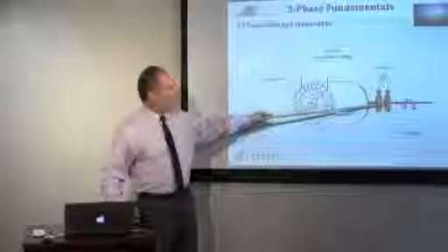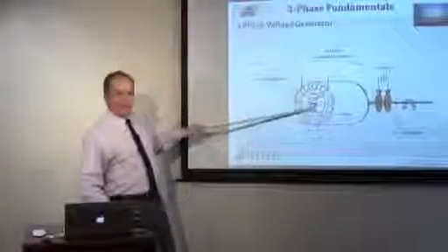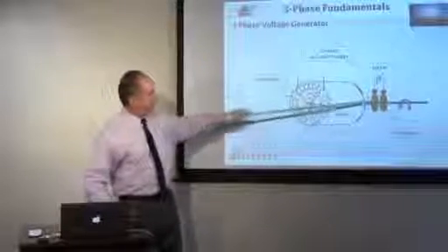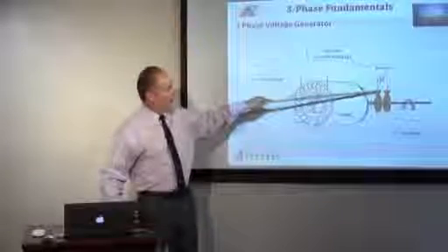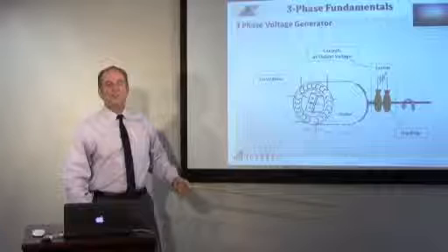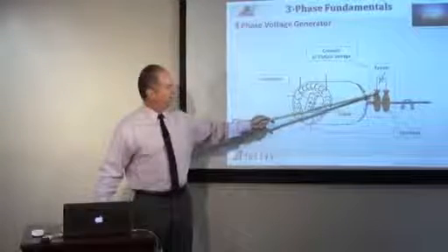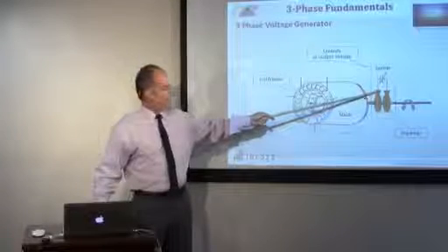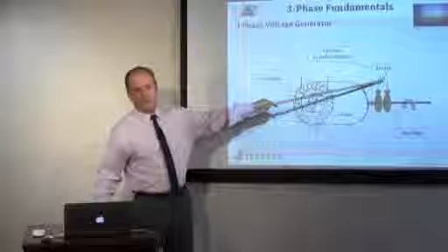It has slip rings connected to the shaft so that the 2 wires from the coil can be connected to the outside world, or the stationary side, through slip rings, which are almost like disc brakes on a car, but you're making metal contact, electrical contact here through the contactors, and then you have a DC supply.